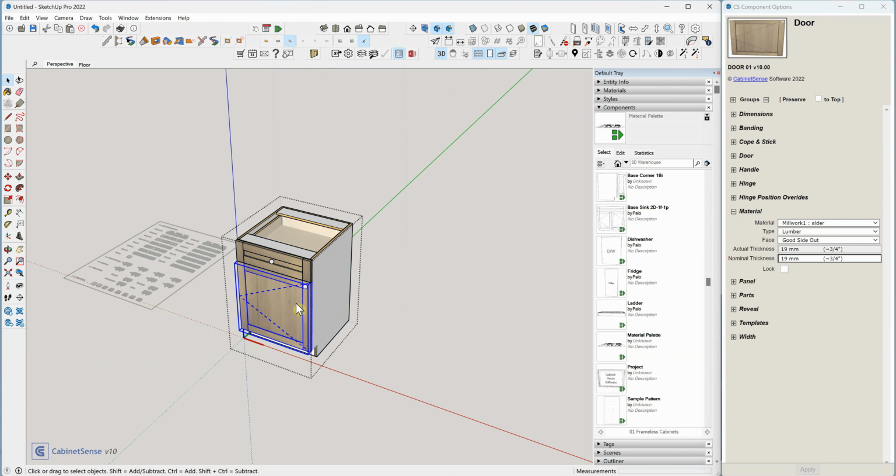So we'll go in. We'll find that 3/4 inch thickness right here, sheet good and alder with particle board. And we'll go in here and we'll say it's 0.76 of an inch. Now when we click on that end, you can see that the actual thickness now is no longer the same as the nominal. The nominal would have been the parent because we've got it set at 0.